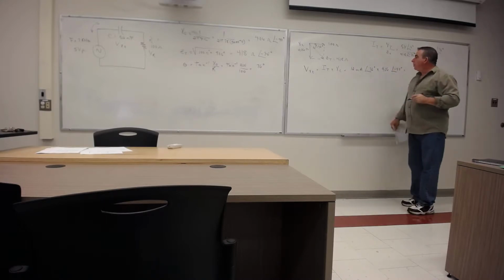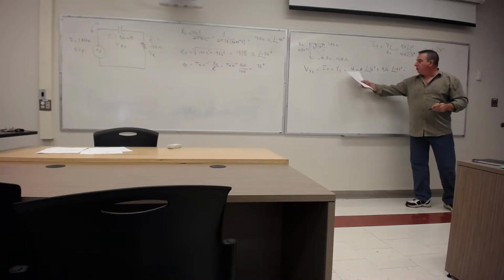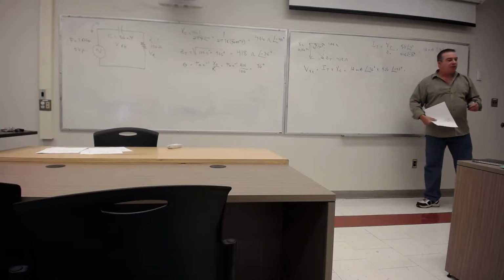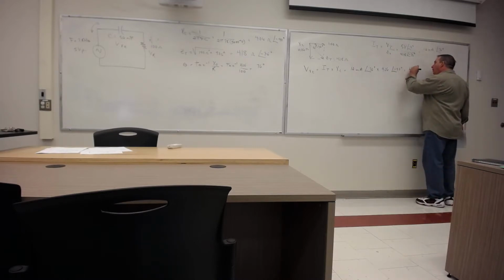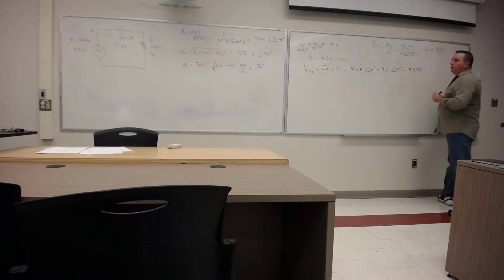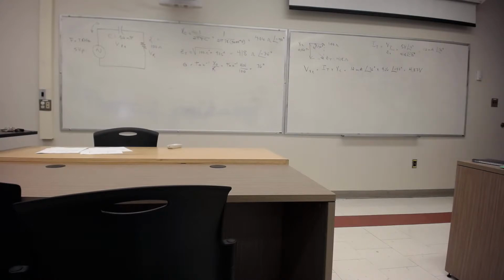All right, so the rule here when we're multiplying is very simple. We're going to take our 12 milliamps times our 406. Do that for me if you haven't done it yet. So take 12 times 10 to the negative 3 times 406. 4.87 volts. Does that work for everybody? Try it out on your calculator. Don't just take his word for it. It's going to verify everything.